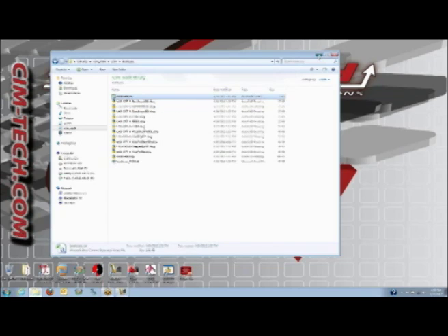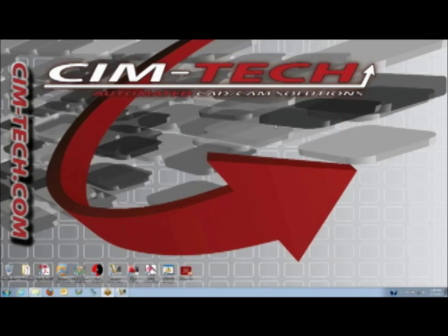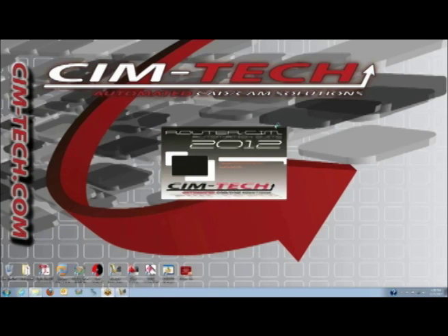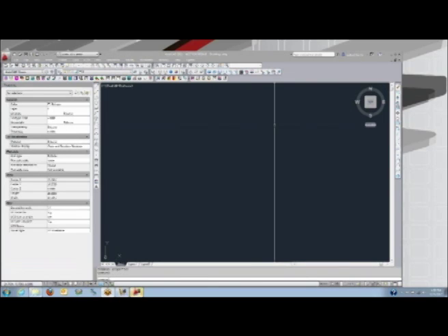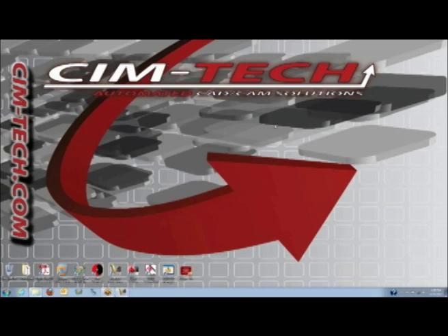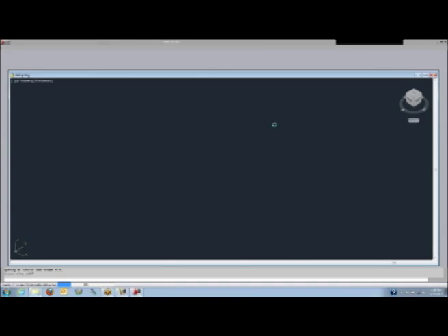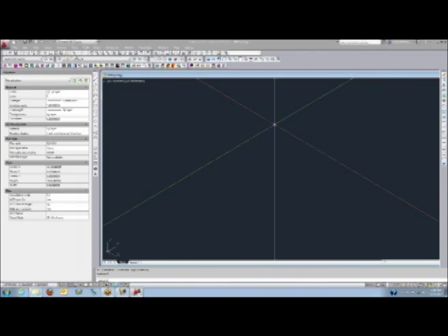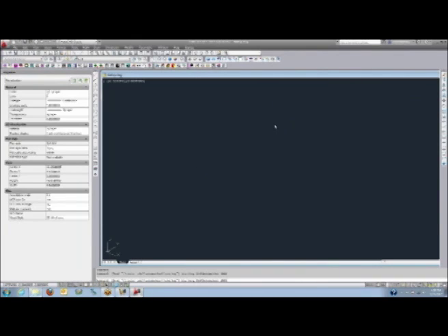The part is imported and the parts are cut and nested. So it's literally just 2 clicks to go from the Inventor model all the way through to cutting and nesting the parts. Now I'm going to get programs for each of the individual parts. I'm also going to get the programs nested together, so we generate programs for single parts and for nested sheets. That's useful if a part moves or falls.